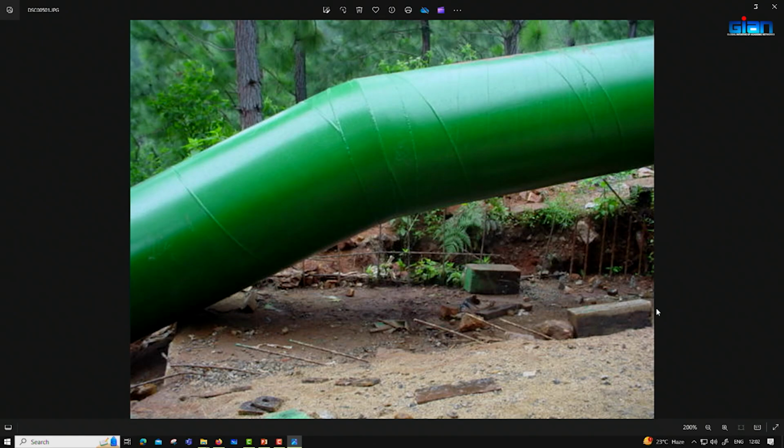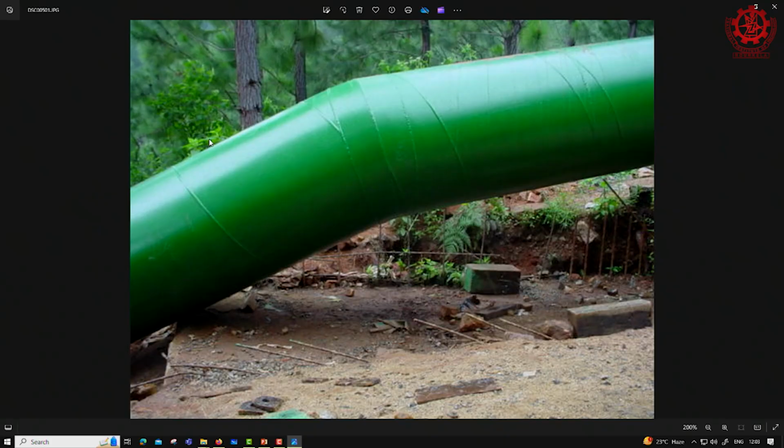Here is another bend. You can see the foundation of the anchor is done already, and some reinforcement also. On top of this they will complete the anchor. You can see the pipe fully finished and fully painted, otherwise corrosion will develop, even inside the concrete, because there may be defects in the concrete, and therefore water and other moisture can accumulate and finally damage the pipe. Therefore, you must thoroughly finish it with the approved paint scheme and then do the anchor on it.